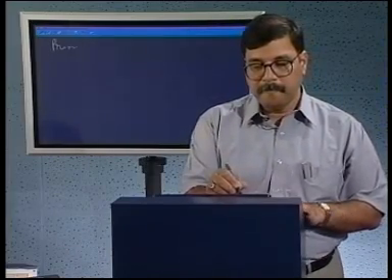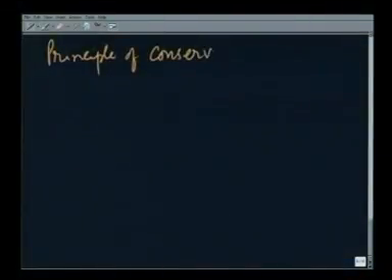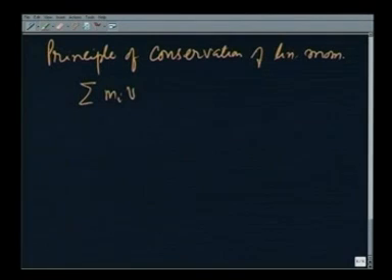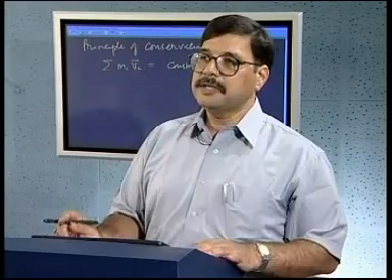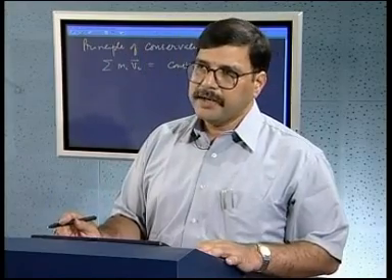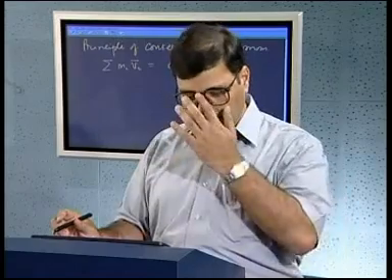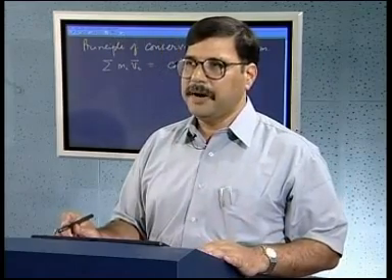The other principle is going to be the principle of conservation of linear momentum, and that tells me that summation m_i v_i is a constant if there is no external force. Since the interaction time is very small, we neglect any external force impulse that may be acting on the particles.